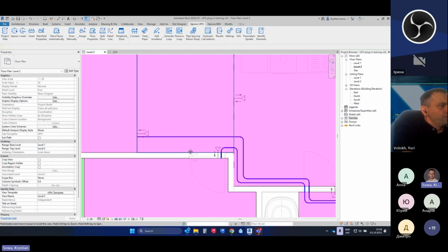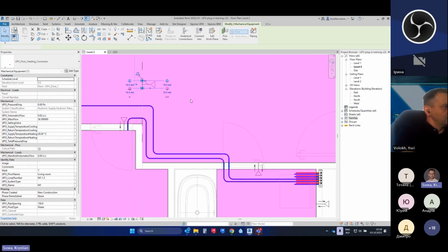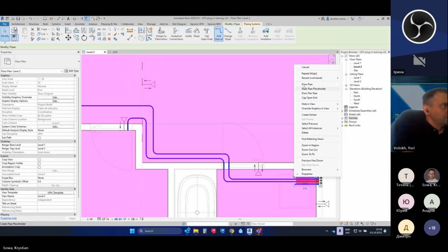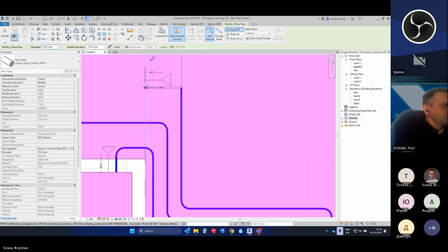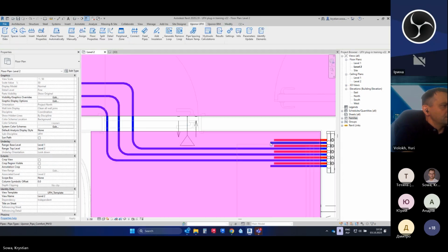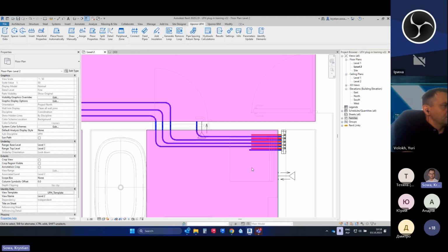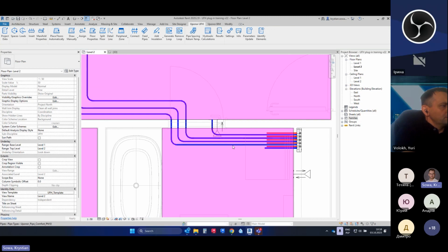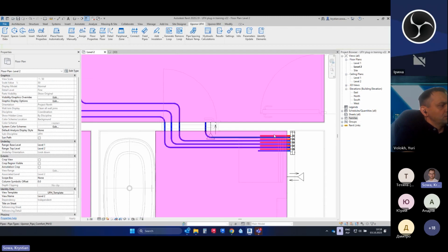So I will just draw, as you said, only the return pipes. Now this one. The last one in here. Okay. And of course I just draw only the return. You can of course draw the supply the same way. So draw pipe and draw it like that. But you can also use the option here on the feed pipes icon. So if you expand feed pipes, it will be the icon generate. So now if you click generate.